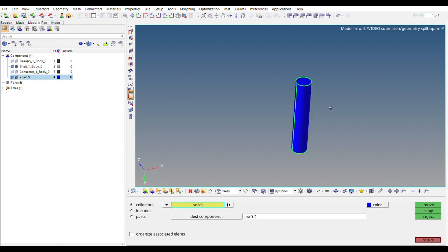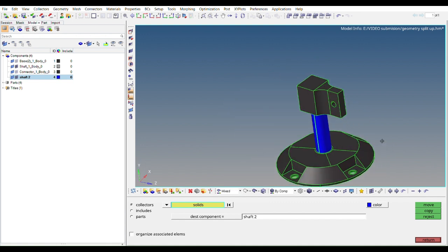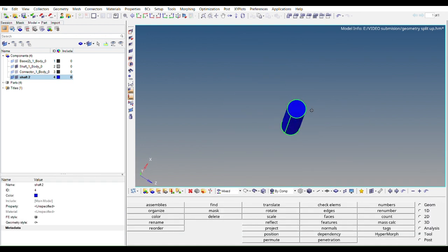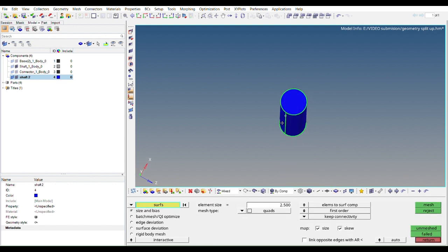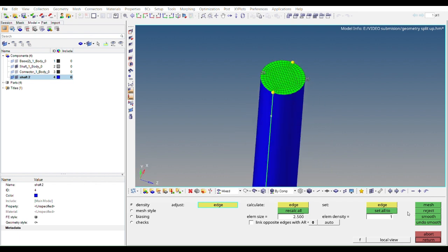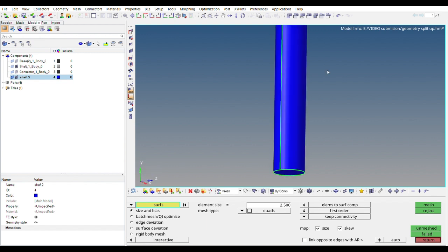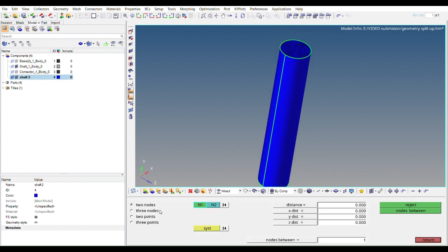Let's start with the hexa meshing. For doing hexa meshing, we have to mesh a face. So let's mesh this. Total 25 components are created. I want to drag this meshing up to this end, right? So what I will do, I will check the distance, go in distance, 2 points, select this point and this point. So the total distance we can see is 2.53. Just copy this and go to 3D.